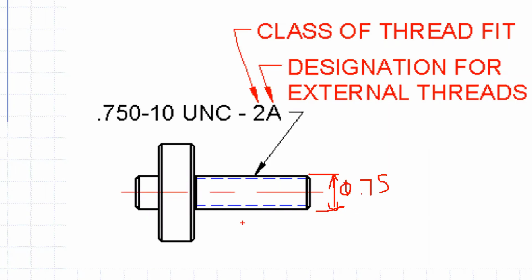I don't have it in here with me, but I will bring it in here. And you can look that up in the machinist handbook and make it exactly right. But you know what? It's a symbol. I don't care how far down that hidden line goes. It needs to be far enough down you can distinguish it from the object line, and not too far down it looks like something else is going on, right? It just needs to look about right. Does everybody understand that?